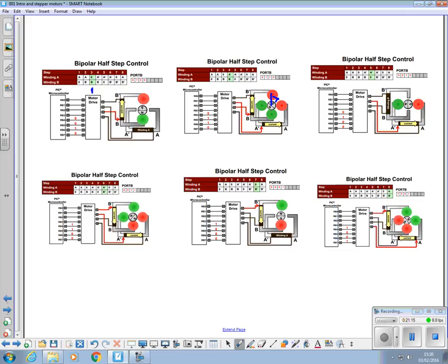That means we've halved our step angle. So we can move in half the steps we did originally, just simply by doing the switching algorithm over. And that's the reason for having the double on coil in the first place, and then we can turn one off and turn it on in the opposite direction the next step and so on, and go round in an 8-step sequence instead of a 4-step sequence.